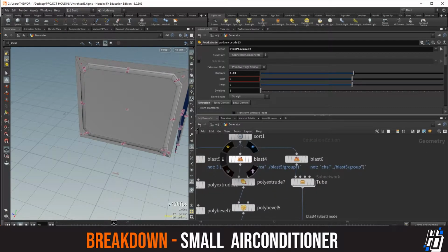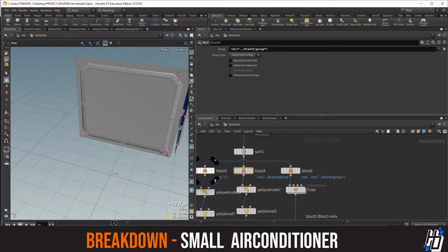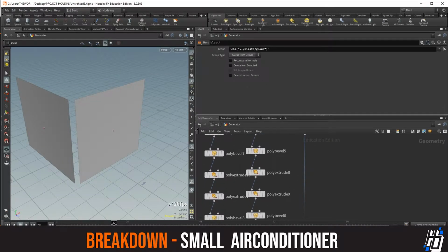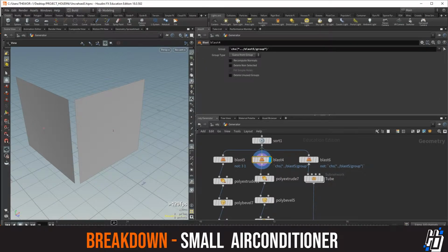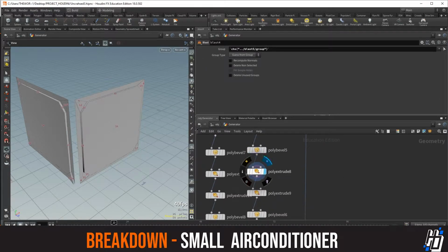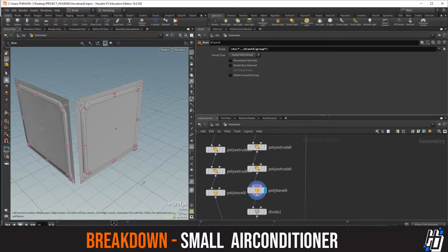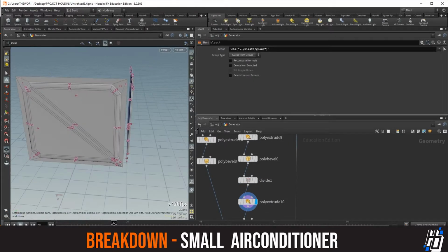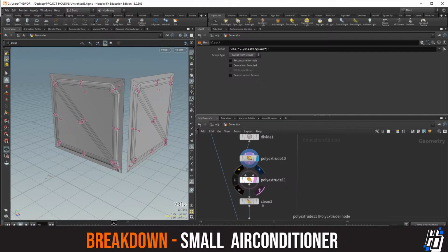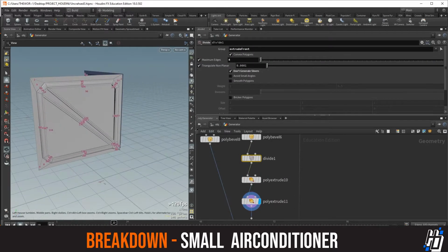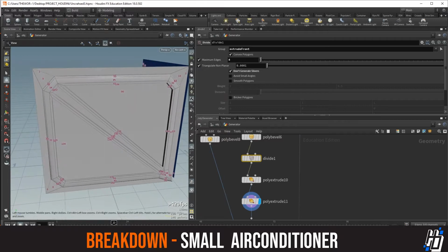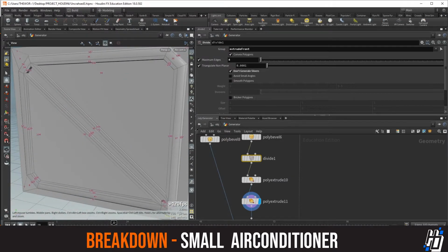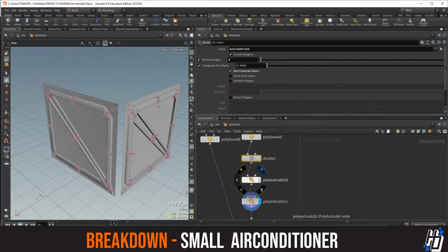And with the other ones, for example here, I say copy this 3 and 1, but don't select 3 and 1, select the opposite faces. So here I tackle the other faces. So with this face, I wanted a bit more detail because there's not gonna be a pipe here. So I did a bit more detail in it. Used the divide. As you can see, the divide is a really nice node to make these cross sections, which can be found in the tutorial that Simon did.